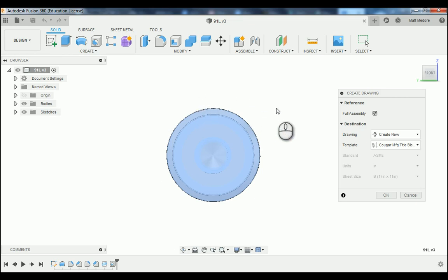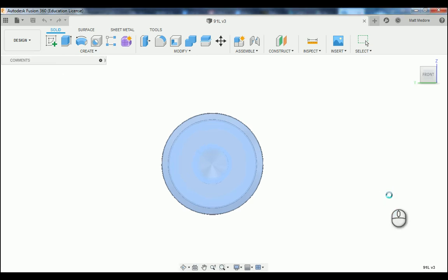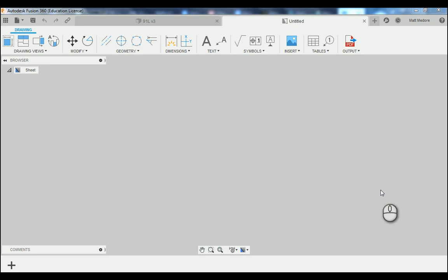The very first view that Fusion 360 is going to land for us is our front view, but we're going to change some information in our pop-up window. We're going to change its style to visible edges, its scale to a 2:1 ratio, and we're going to turn tangent edges on.